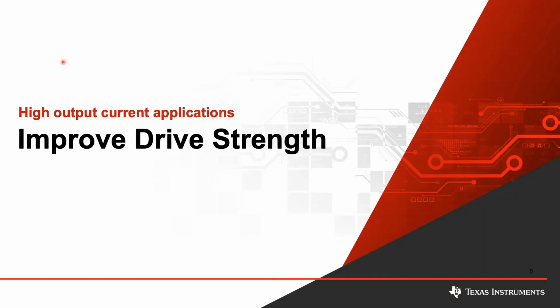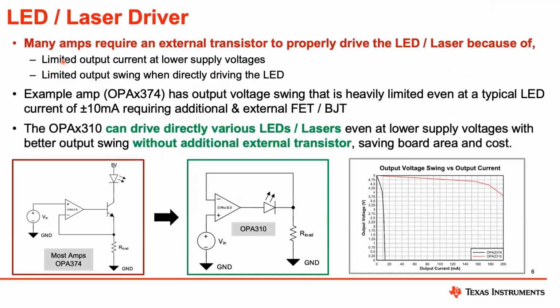All right, hello everyone. I'm Robert Clifton, and as Bhuvanesh mentioned, let's talk about the improved drive strength of the OPA 2310 from an application perspective. So let's start off with the LED laser driver applications. Many amplifiers require external transistors to properly drive the LED, mostly because of two different characteristics. First, the limited output currents at lower supply voltages, and second, this is the one that most people forget about, is the limited output voltage swing when directly driving the LED.